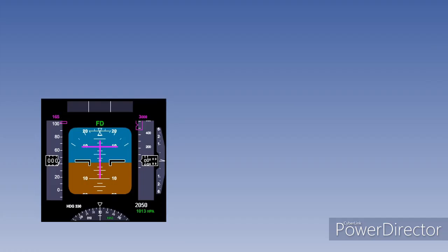During departure, with the flight directors selected on, the crew have 2 methods of displaying a pitch demand on the primary flight display. Firstly, they can bias the pitch demand manually to a pre-calculated setting, which is displayed on the primary flight display. This gives the pilot an initial body angle to aim for after rotation.